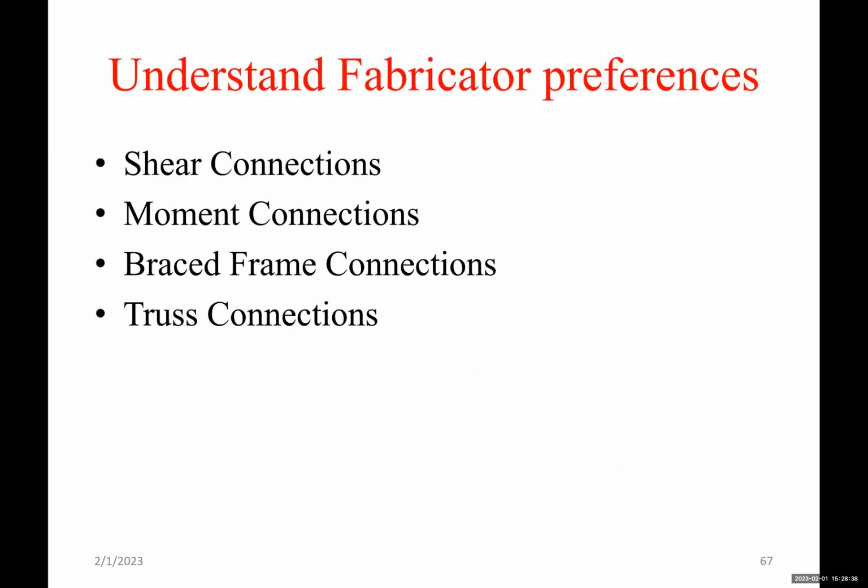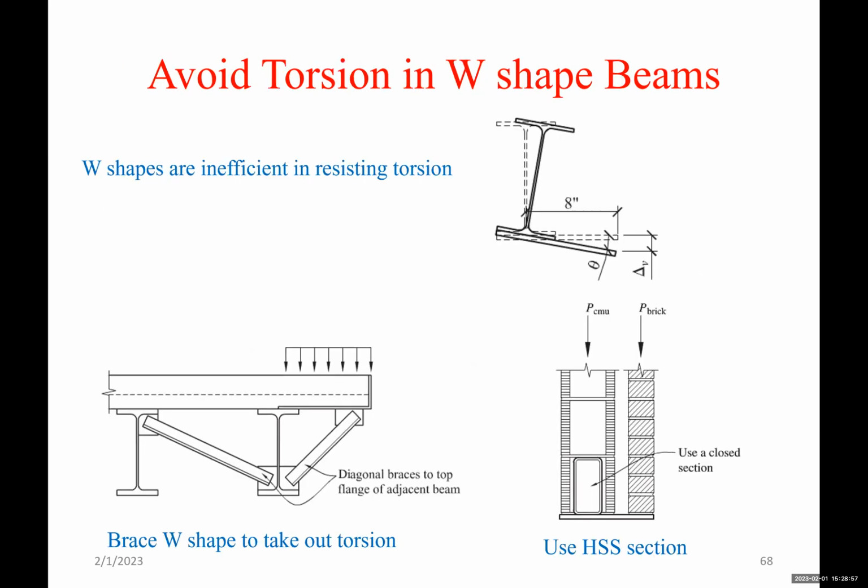Understand the fabricator's preferences: shear connections, moment connections, braced frame connections, truss connections, etc. Try to understand. Today, many jobs are design-build, so you'd have a fabricator from day one. Try to understand what their preferences are. This will simplify things in the process.